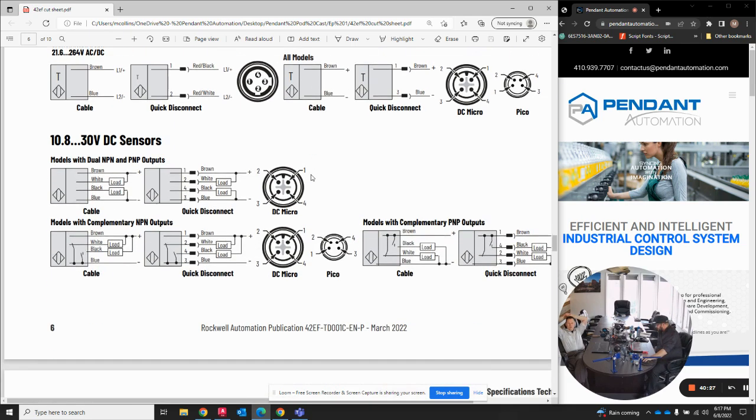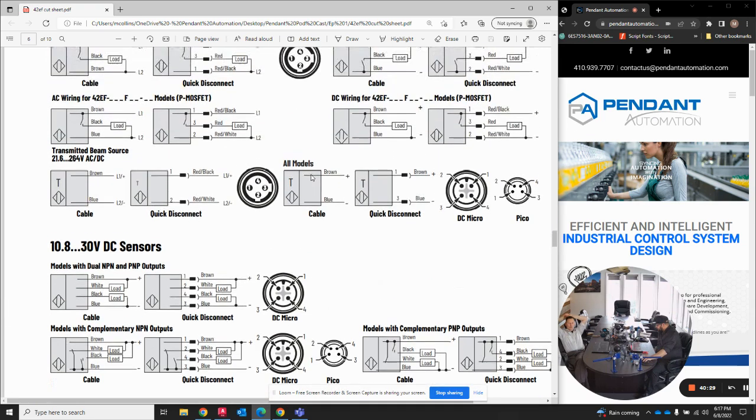And so I understand that they're much less costly for electrical installation, but 120 volt controls are a thing of the past. One thing I get asked quite often, because you have whether the sensor is going to be PNP or NPN, but then you also have light out, dark out. Which we're going to talk about next. That's operation. And go ahead and pause it here for a minute.